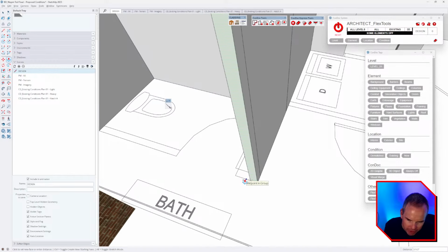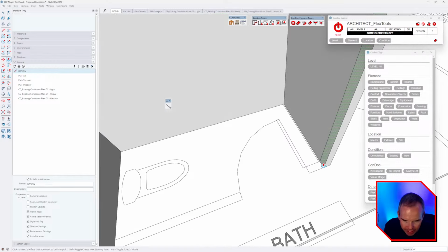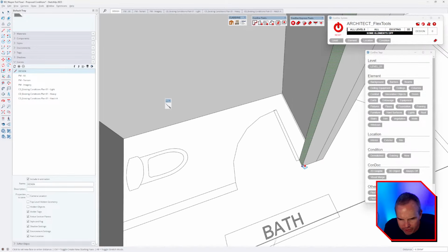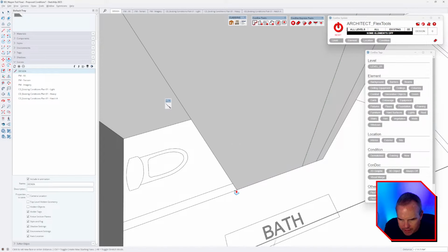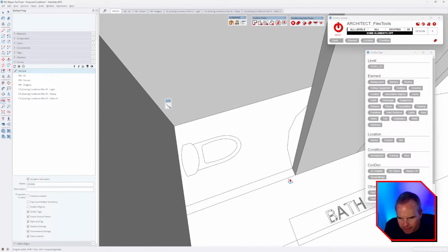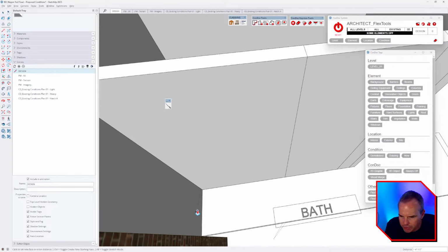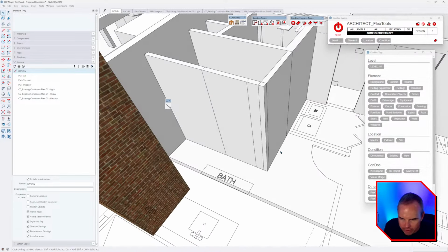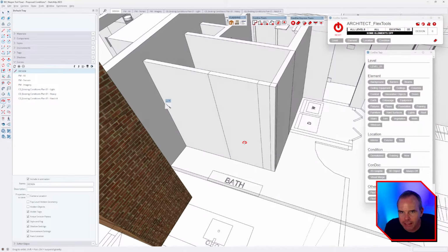And then I'm going to pull this out. That one is at 3.5, so maybe it was just that wall. That was kind of goofy. I'm going to pull it across and snap here, and then pull it across and snap there, and then pull it across. And notice that I'm using that push-pull tool, and I tap Control, and then we can leave a copy of the starting face behind.